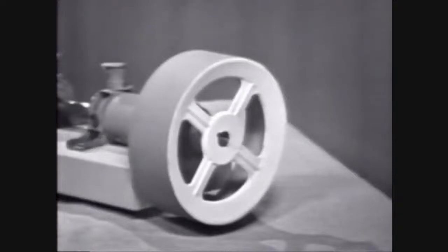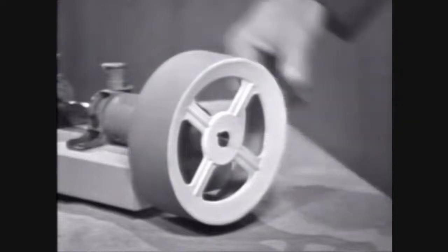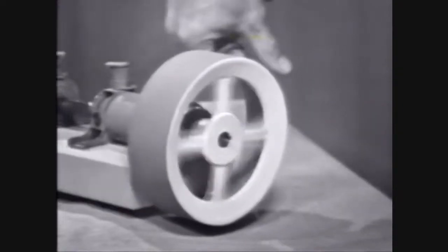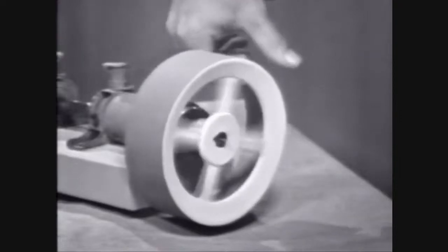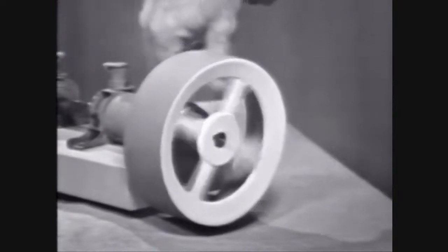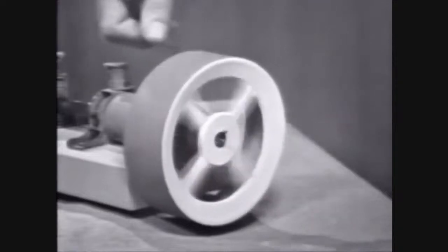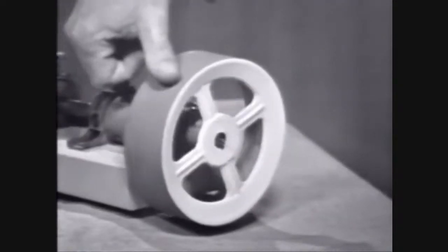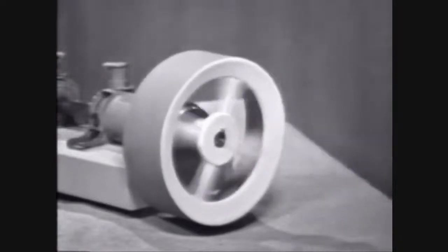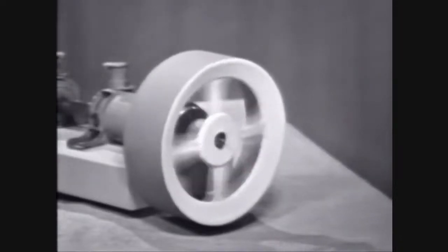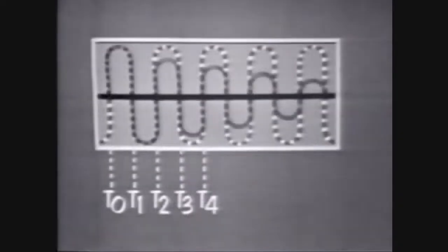The ringing action of the LC circuit is often referred to as the flywheel effect, because like a flywheel, once it's started, a small amount of energy added at the right time and in the right direction will keep it going. And also like the flywheel, if energy is added in the wrong direction, the flywheel will stop. So energy must be added at the right time in the LC circuit. For example, if a positive voltage were applied at time 2, the energy lost in the first cycle would be replaced and the amplitude brought up to the desired value.